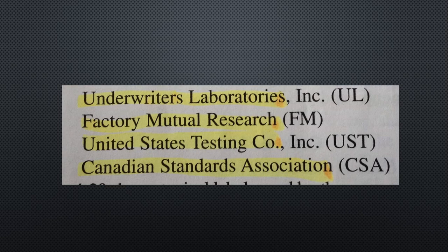As part of the electrical standard, OSHA requires that electrical equipment and materials be listed, labeled, accepted, or certified, providing that such equipment is available. A non-listed, non-labeled, non-certified component may be used only if it is in a class not tested by a nationally recognized testing laboratory. Should that be the case, the object must be inspected and tested by a recognized organization.